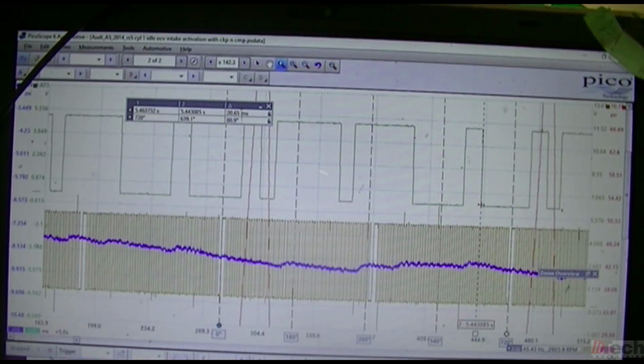But again, I'm doing and checking this advancement testing to check and see the phasers on the intake, being that the code again was related to an intake cam area, the intake cam performance or timing, and so I wanted to just see. I'm trying to just narrow down what is going to be needed, being that this is such a big job to do.